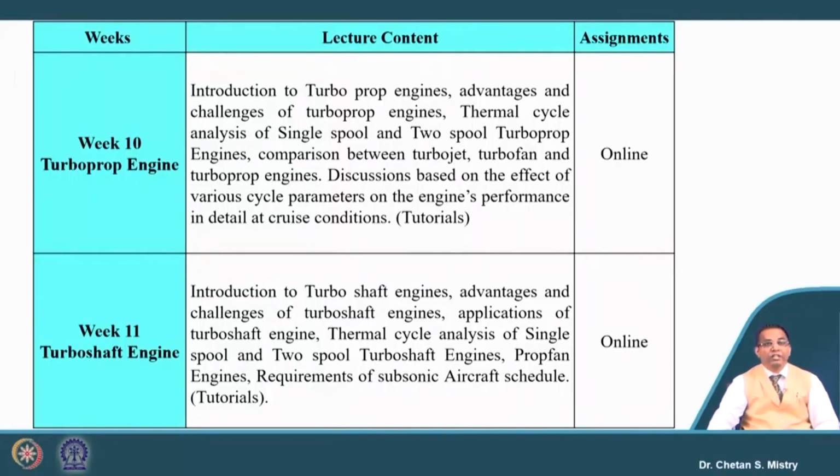So you can understand these engines we are discussing are gas turbine engines. They have a special mission, a special requirement. If we discuss the turbojet engine, we know the whole purpose is the generation of thrust. Similarly, in the turbofan engine we are also generating thrust, but there we have cold thrust and hot thrust. Cold thrust is generated by the fan exhaust, and hot thrust is generated by our core engine.